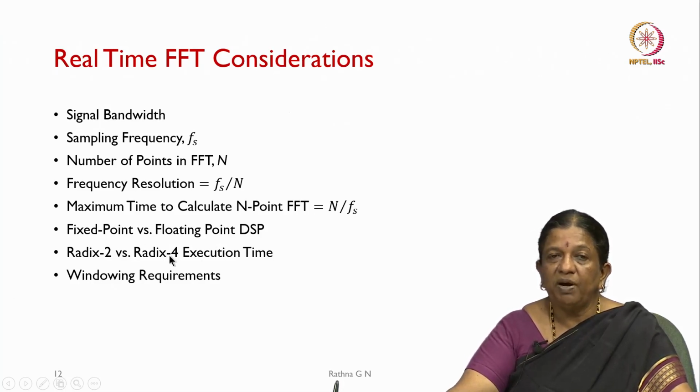So, if the input is a power of 4, it is advantageous to use radix 4, because the coefficients we have to compute in radix 4 are -1 or -j. You can refer to the literature on how to do the radix 4 implementation. We have seen radix 2 here, where we divided into even and odd parts and then computed.